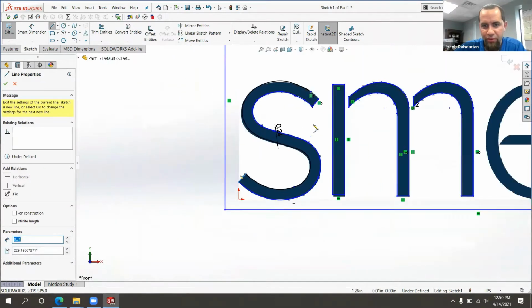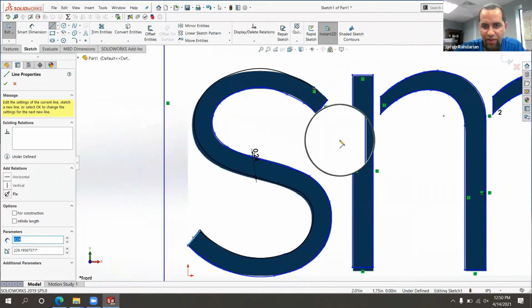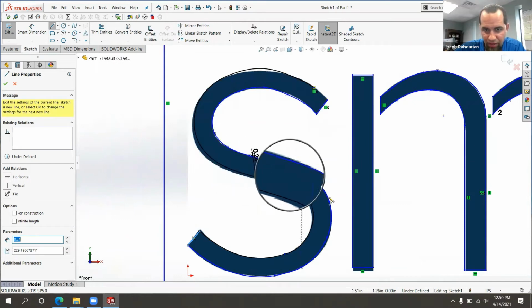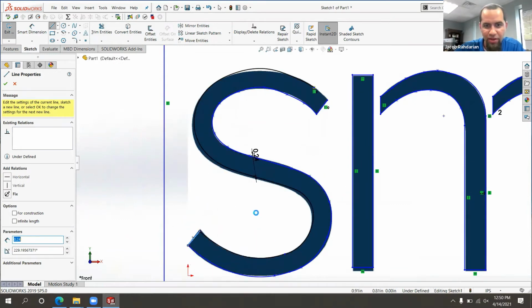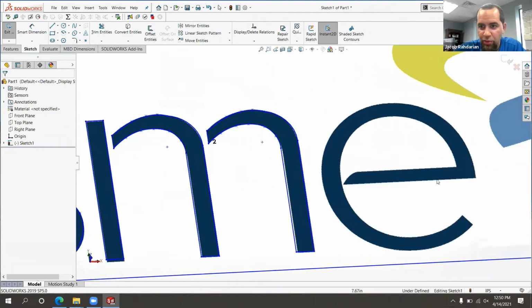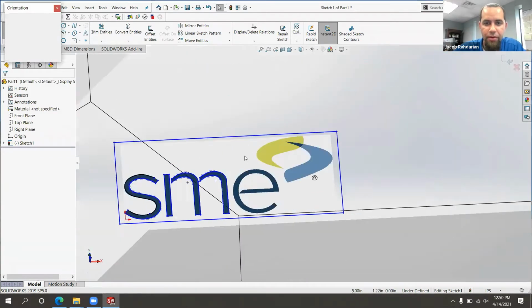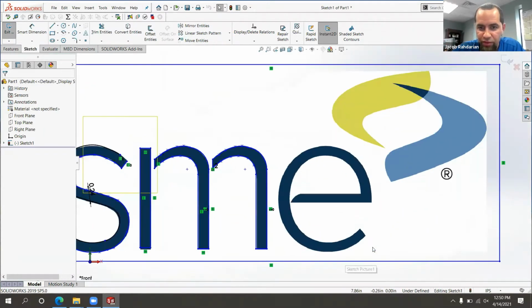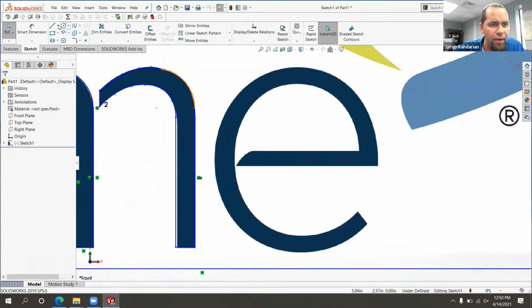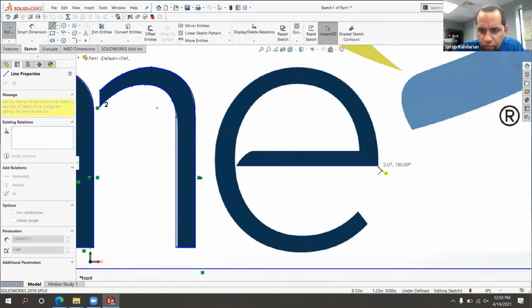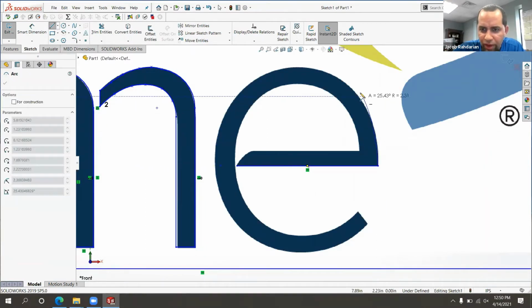One thing that was kind of a helpful trick is if you tap the G key, it'll open this magnifying glass, so you can check if you have any gaps in your geometry that don't make a full chain. That would create some issues when you go to try and extrude it. Also, you could tap the space bar key and it gives you some quick access to various drawing views. Toggle the A key again, get this arc command back going for us.